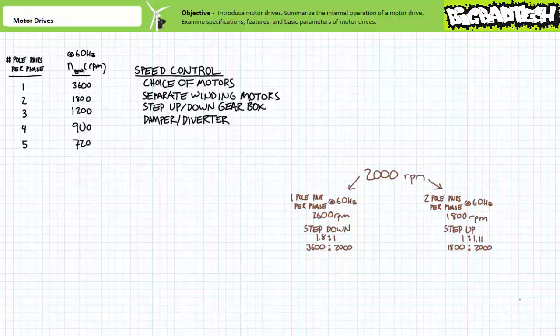In both scenarios, an ample amount of energy is constantly being converted, only to be wasted when less input is required. A far better scenario for those applications necessitating a range of speed values is to think from the bottom up. Long story short, rather than constantly hammering on the gas and intermittently applying the brakes, let off the gas when you want to slow down and step on it when you want to speed up. What is required for applications necessitating variable speed is quite obviously a variable speed motor. Various methods of speed control exist.